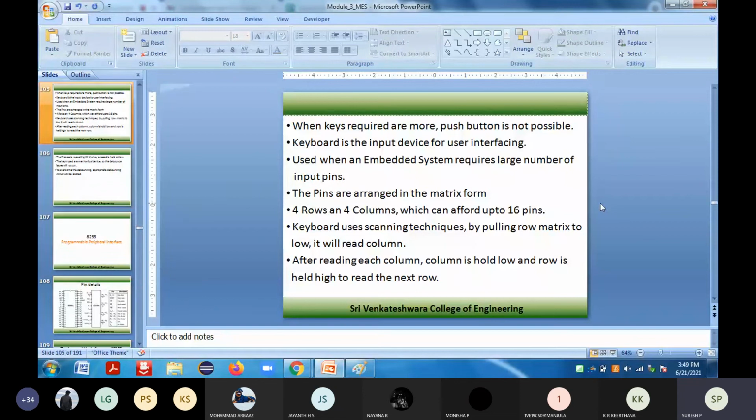Here also it is the same thing. Whenever you press the key, you should not get the wrong value. So to overcome the wrong value being entered: if I press 4, the 4 has to be there. For example, if 3 was there previously and I press 4, it should not oscillate between 3 and 4. It should get the value 4 directly, changing from 3 to 4. For that particular reason, we make use of the debouncing circuit in your keypad.